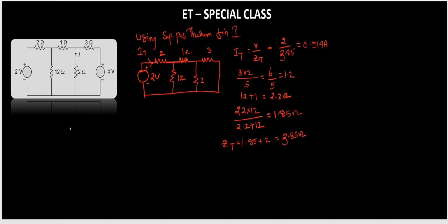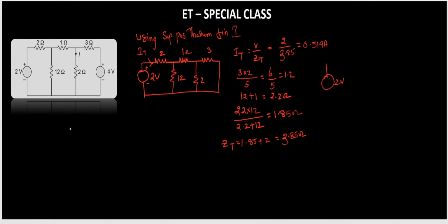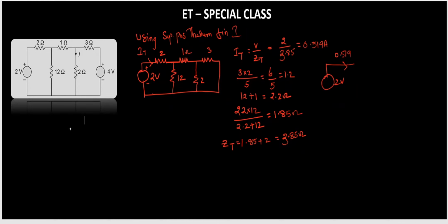So this 0.701 is dividing here. The voltage here is 2 volts. From here the 0.701 is being divided across the 12 and the total equivalent resistance here, which is 3 and 2 giving 1.2, plus 1, that is 2.2. So calculate the current that is going into this 2.2. This is 12, this is 2.2.